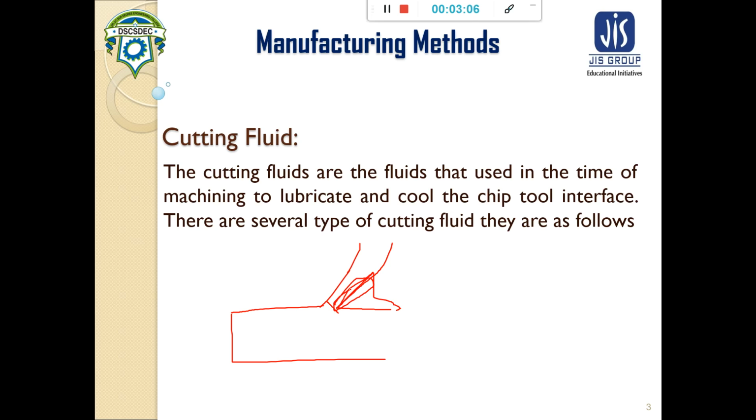So this chip tool interface is subjected to a high rate of friction. Due to this high rate of friction, what will occur? The temperature of that position will increase. So some very serious defects may occur in the cutting tool, and that will lead to wear of the cutting tool. That means the tool life will be lesser if we do not use the cutting fluid.